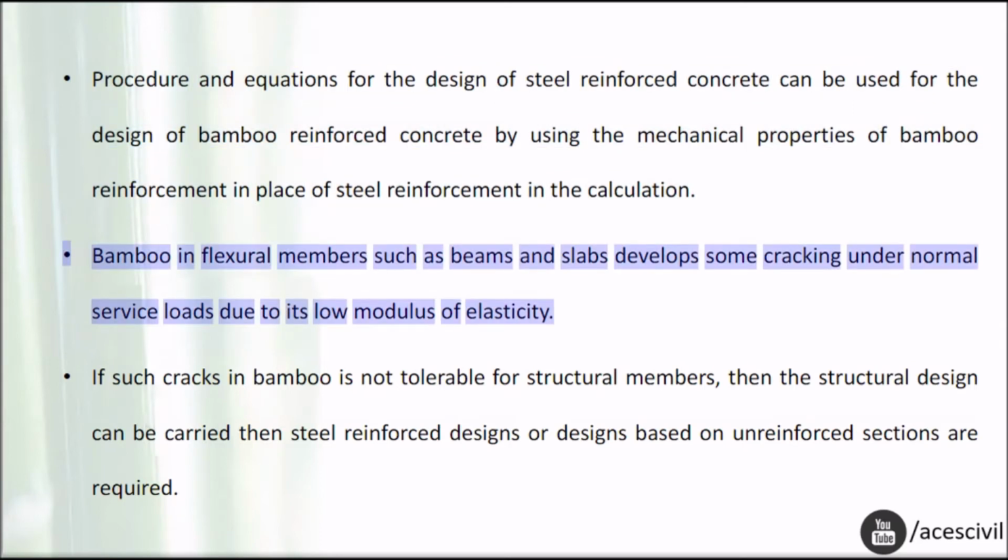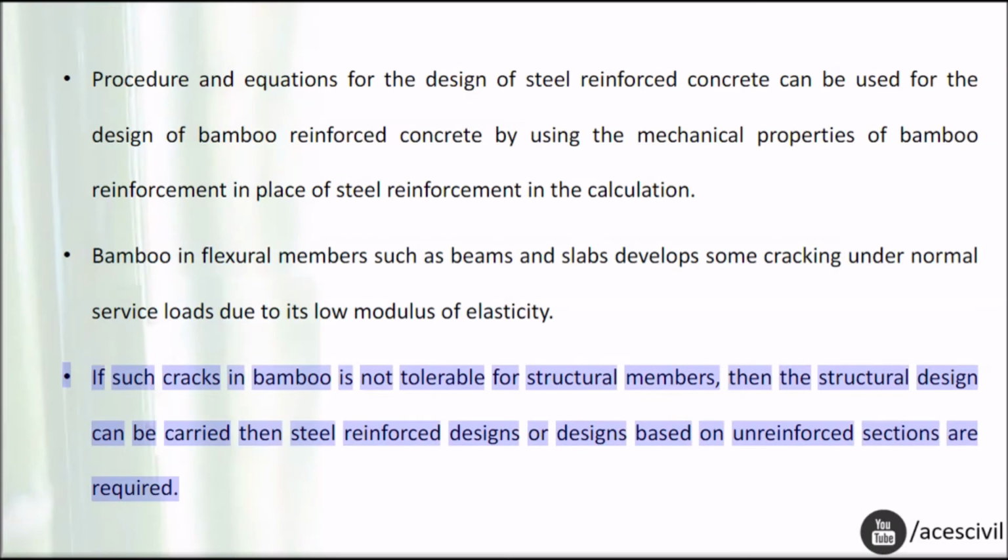Bamboo in flexural members such as beams and slabs develops some cracking under normal service loads due to its low modulus of elasticity. If such cracks in bamboo are not tolerable for structural members, then steel reinforced designs or designs based on unreinforced sections are required.